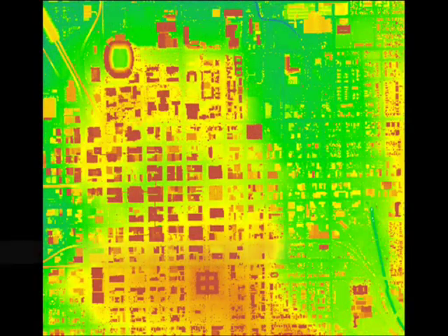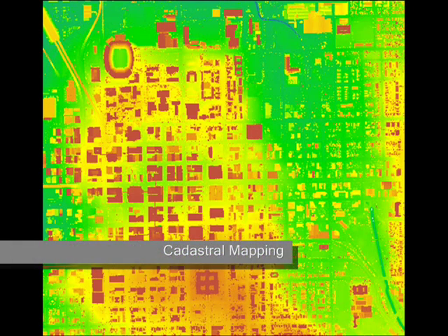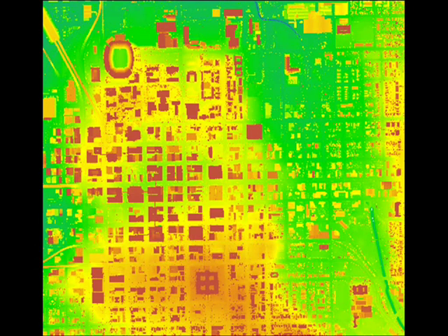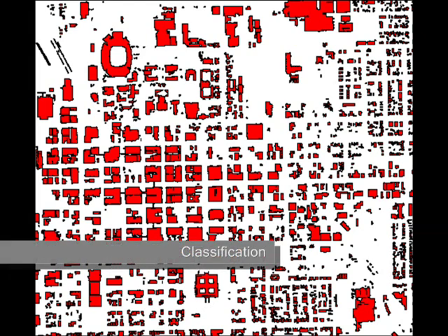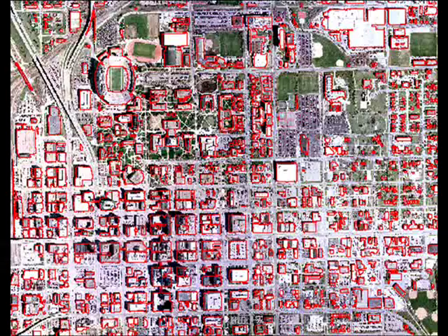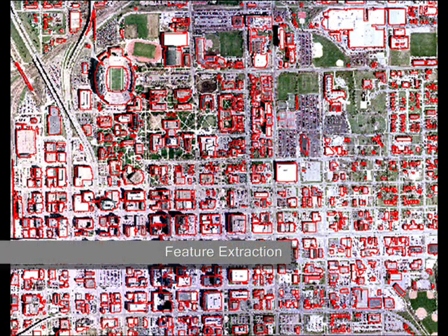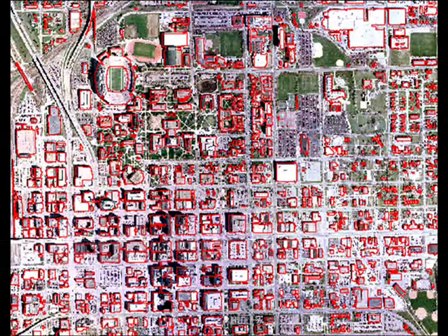Classification techniques also make LiDAR a very useful tool in cadastral and other infrastructure fields. For example, using LiDAR data, building footprints can be delineated by successive classification and eventually extracted as vector features. This technique is not perfect and requires additional processing in most cases, but is generally less labor-intensive than many traditional methods, such as digitizing from orthorectified imagery.